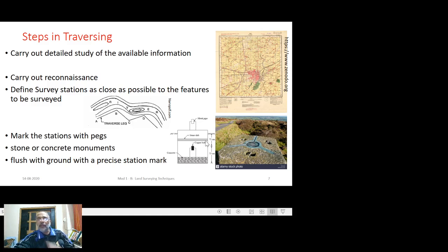It is covered with some material so that it won't be disturbed, and in order to facilitate the surveying operation, it is provided with a stake and a nail mark so that one can work on this. Whenever the survey is completed, this structure will remain buried, and one may refer to it by making use of location sketches, as they are called.